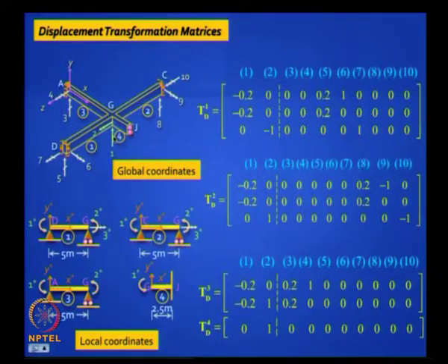You will have chord rotations. Let us take the first element. Will you have an anti-clockwise chord rotation or clockwise? Anti-clockwise, which means you will have clockwise equivalent end moments. So you get minus 1 divided by the span, which is 5. So 1 by 5 is 0.2. So you get minus 0.2, minus 0.2. Is it clear? And you do not get anything in the third degree of freedom, because that corresponds to an angle of twist. So is it clear what we got here?